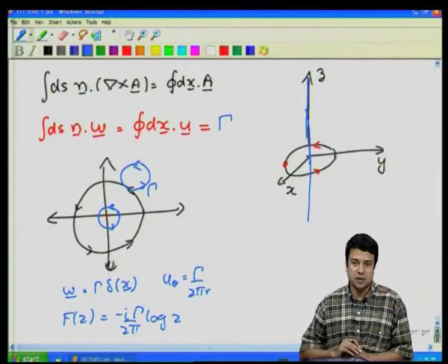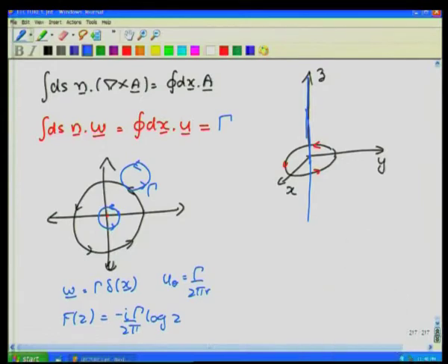In the next lecture, we will look at some more complicated forms, in particular the flow around a cylinder, and our objective will be to calculate the net force that is exerted for the flow around a cylinder in 2 dimensions in a manner similar to the force that we calculated for a spherical object in the last class. In that case, we found that the net force on a sphere has to be 0, because there is no viscous dissipation. In this case, we will see that it does not have to be 0. The net drag force along the direction of velocity has to be 0, but the net force perpendicular, what is called the lift force, does not necessarily have to be 0.